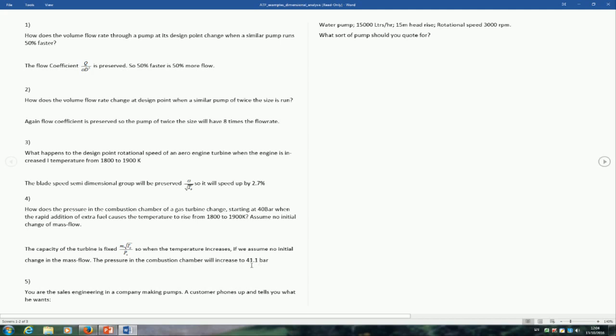This process is not just an interesting test of your thinking power, but something that's done on a daily basis in Rolls-Royce. The problem with a gas turbine engine, when you've built it, is it's very constrained in the way it can behave, because each turbine is of fixed capacity. The compressor cannot be run across its characteristic because the turbines define a line that it has to run on.